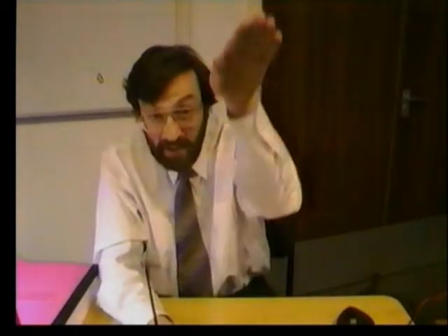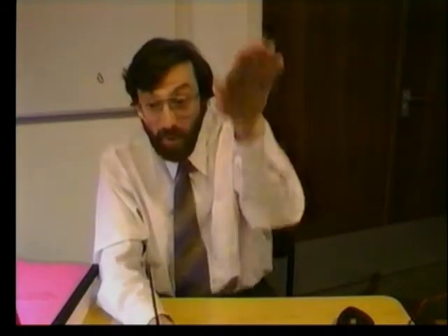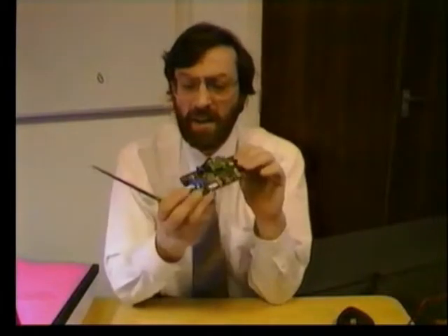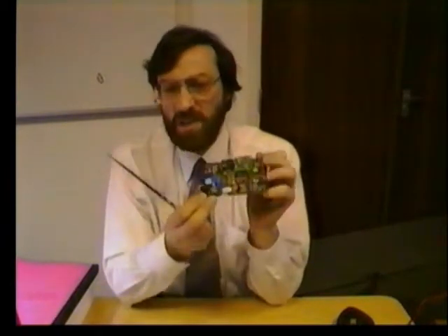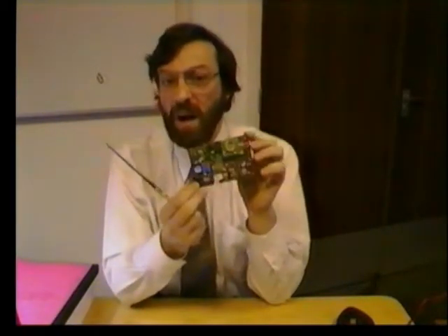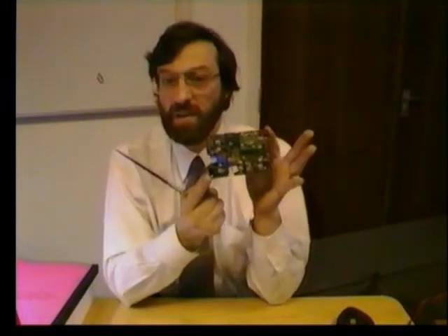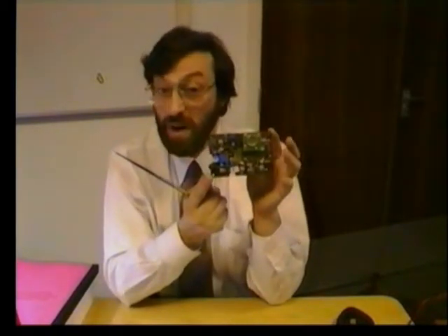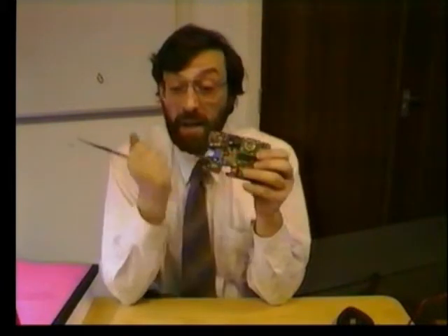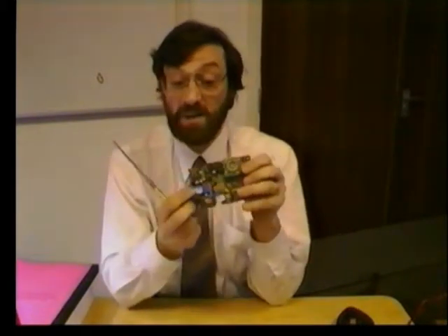How often did the side lights come on or go off? How often did you raise a particular solenoid? If it was a pickup truck, you could be raising a particular lift unit up or down. It will log all that. In fact, it will log an amazing amount of data. Even if you have a smash up, it stores in here the whole velocity profile of the last 30 seconds of your driving up to the point where an impact occurred and the car was smashed up.